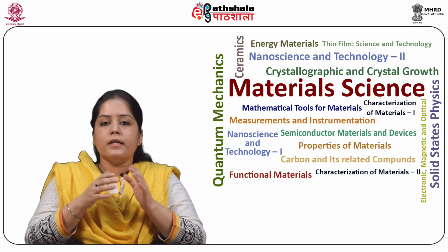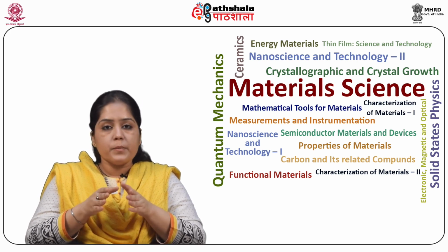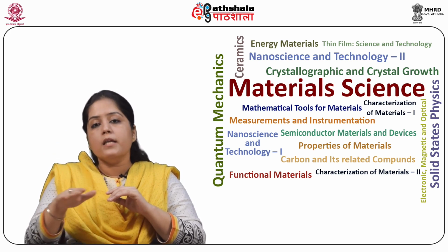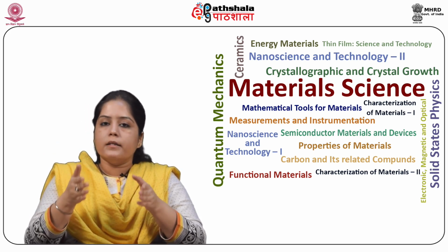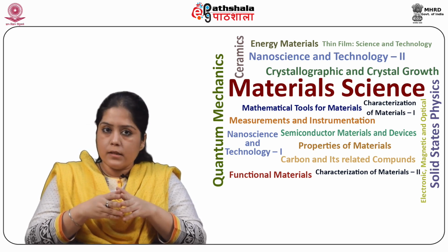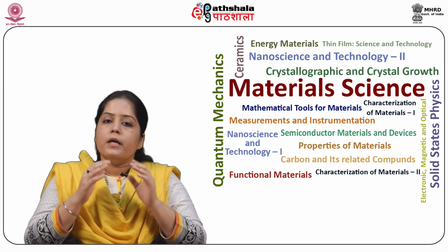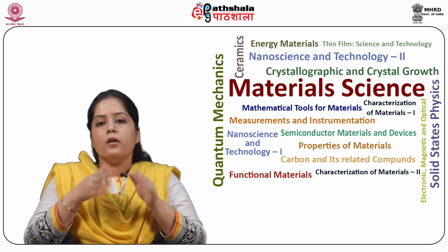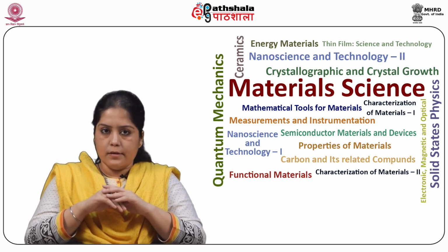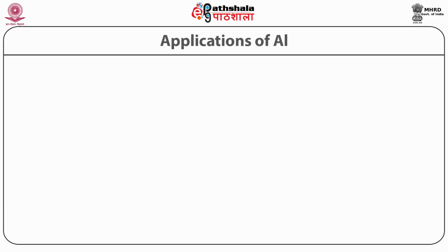7000 series are alloyed with zinc, and they can be precipitation hardened to the highest strength of any aluminium alloy, with tensile strength up to 700 megapascal for 7068 alloy. 8000 series are alloyed with other elements which are not covered by other series, for example, aluminium lithium alloys.